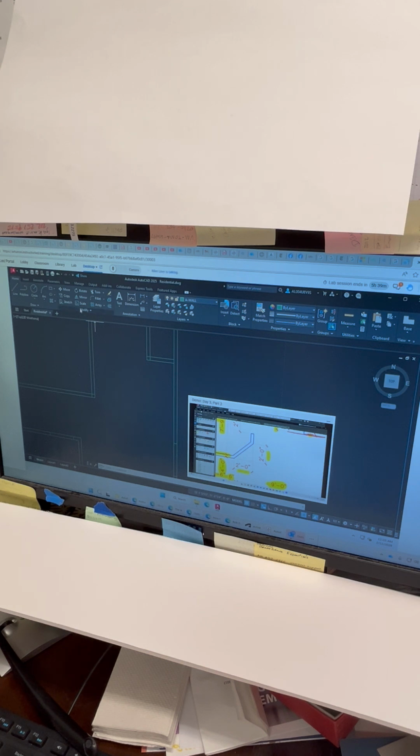This is a chamfer. Now, here, I'm going to just right off the bat try to tell you right now. We only are going to use the chamfer command for this line here, not the other line. So, spoiler alert, what I'm going to have you do is you're going to basically create the chamfer, and then you're going to offset this line 3.5 inches after you're done.